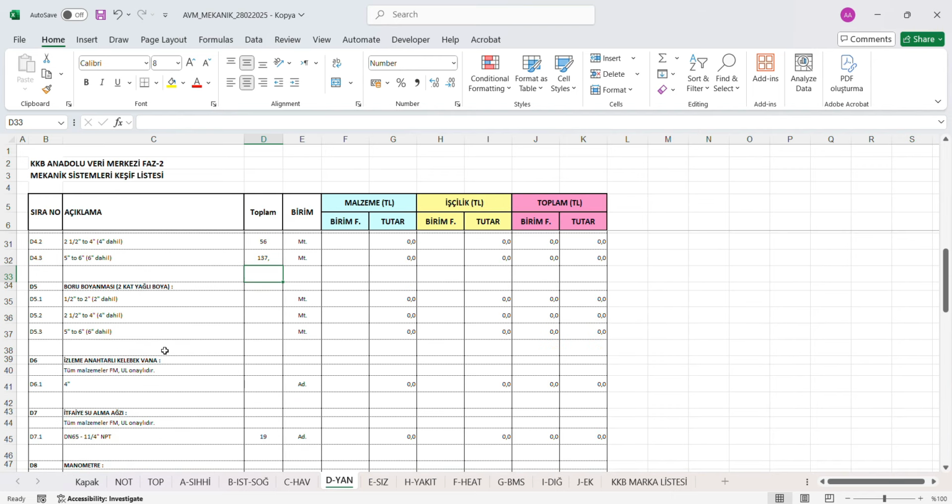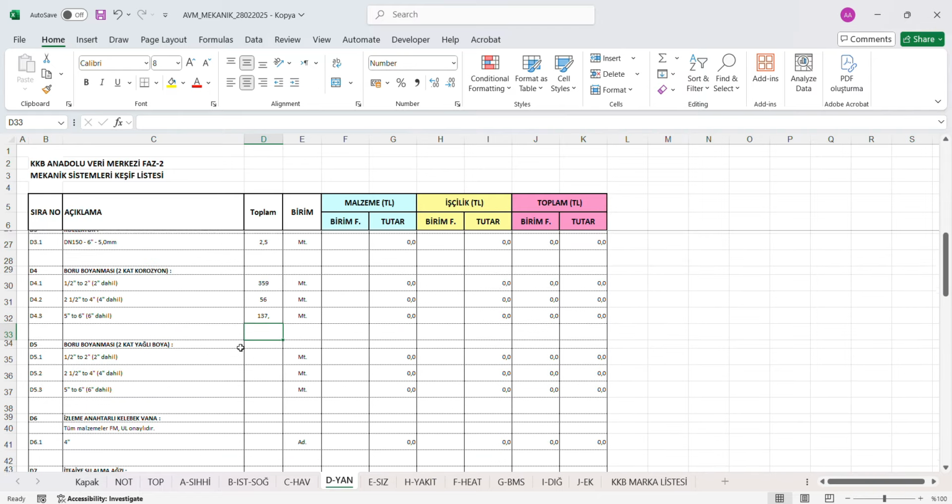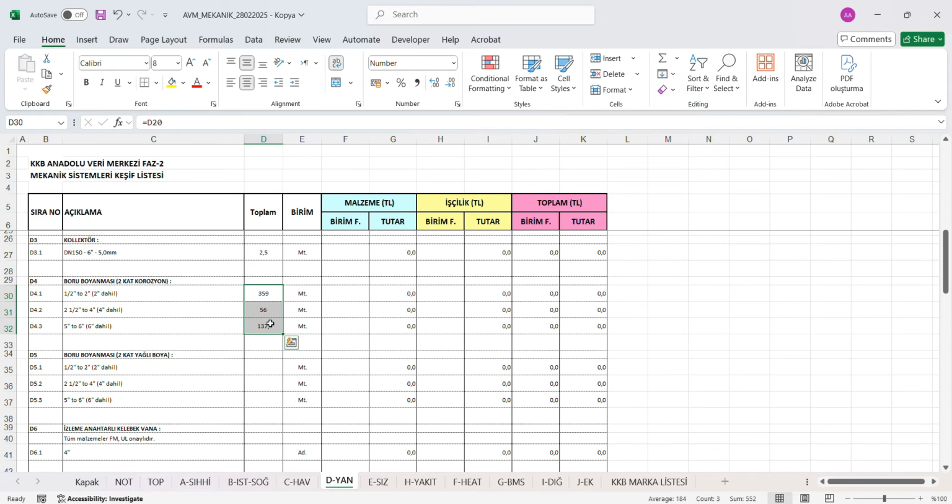Required precautions. Many countries require that the tank holds an adequate amount of water that equals the amount needed to run the system effectively throughout the duration of the fire. Backup tanks. An important requirement is that backup tanks should be provided to ensure the continuous water supply in case of a fire. These tanks should be protected from any contamination that could affect the water quality.